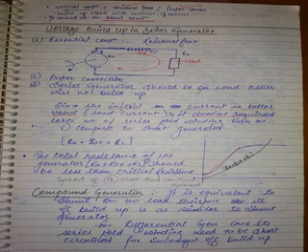If you observe, in the second, it is given critical load resistance. Load resistance is above or below some critical value. We don't know what 12, 10, 10.5, 15, 20 are. There is no theory to explain that; there is a theory to explain minimum voltage and maximum voltage. Between those, there may be some reason which makes the voltage some 12 volts. For example, let us say the load has some value. Due to that load, as the resistance is decreased, the current will flow into the field winding, due to which the flux and all those things will vary, and automatically you are getting some voltage above the minimum value. So automatically it is for 2 only. The context of the question is, how the question is framed means you have to pick 1 and 3, and automatically the second one will be matched.